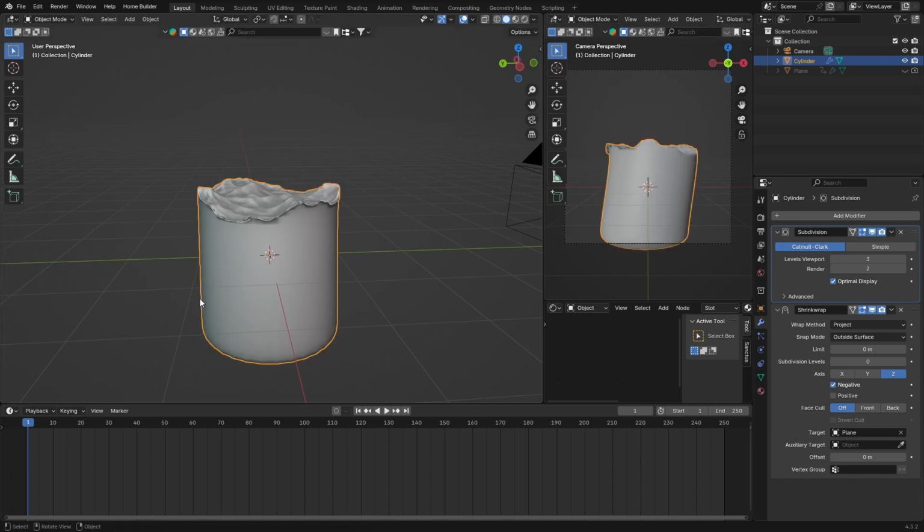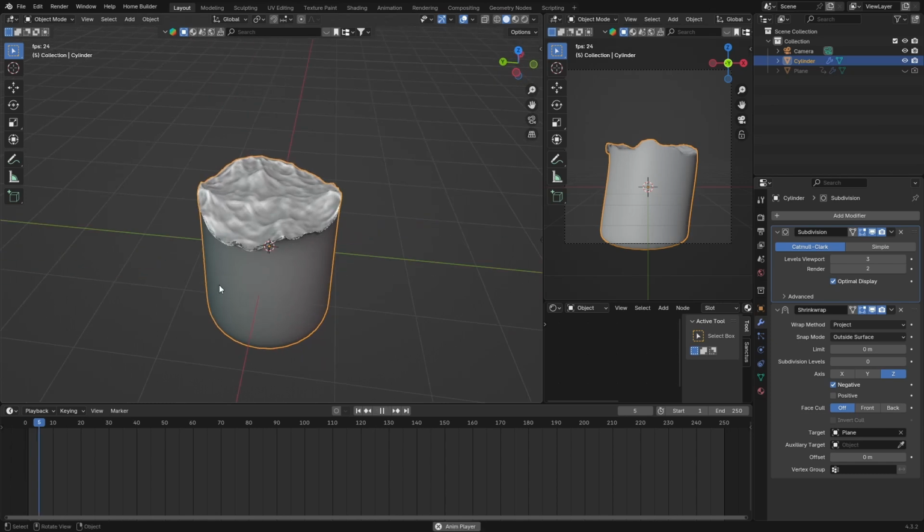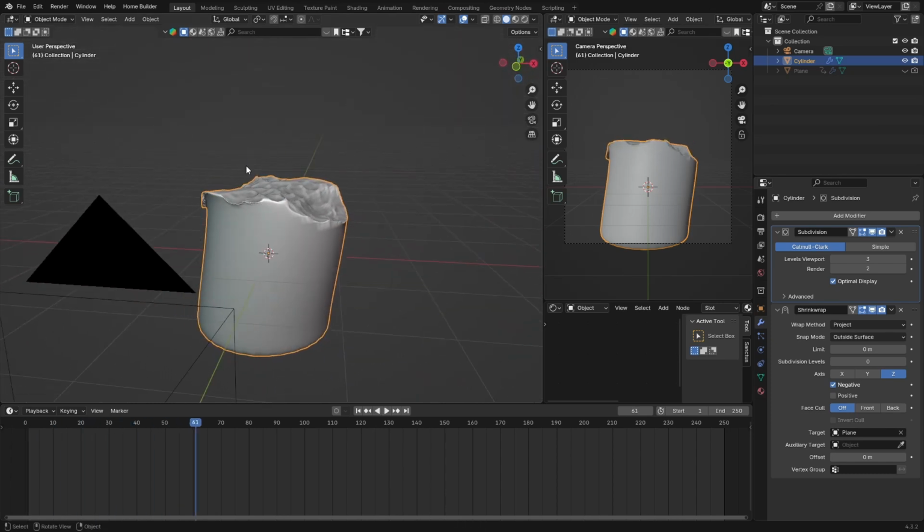And then if I hit Tab, you can see obviously I didn't make it go down straight all the way, but it then makes your object look a little bit better. You'd have to just go back down straight. So just make sure that you're going down straight on the axis. You can just hit the axis that you want when you hit G to grab, and then it will go down straight. I didn't do that, so I'm not going to redo it, but yeah.